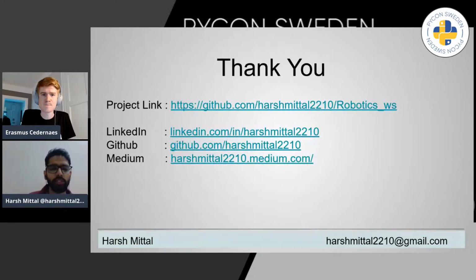Okay, so this is the thing with ROS. The code that you have used for the simulation, you can run the same thing on the Raspberry Pi. All the different libraries are already supported on the Raspberry Pi itself. You just need to install ROS. In that case, your master and client will be on different systems. For example, you can make your Raspberry Pi the master, or you can make your laptop the master.